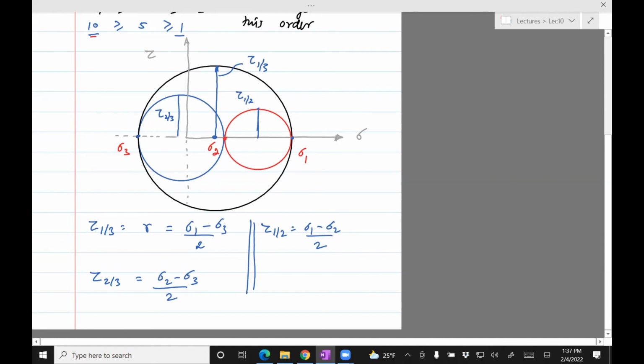Okay, so the reason why we're interested in analyzing a general 3D stress element and drawing 3 Mohr's circles is that when we are designing something for maximum stress, we are interested in the maximum of that, the biggest circle, right? The biggest circle will give the biggest stress. And the biggest stress would mean that that stress is most critical for that particular stress element, which means that when the element fails, it's because of the principal stresses which have the maximum value. So sigma 1 and sigma 3 are going to be critical. Sigma 2 is not going to be critical because it's intermediate.